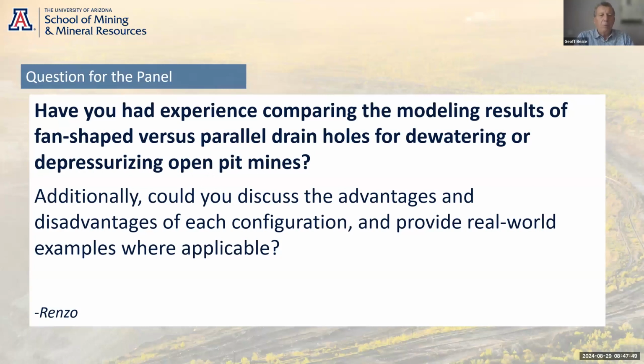If you have variable structural orientations, or your access to the drill or to the face is limited, so that maybe there's only certain places that you can put the drill without acceptable rockfall risk, then you might want to do fans of holes all from the one location.